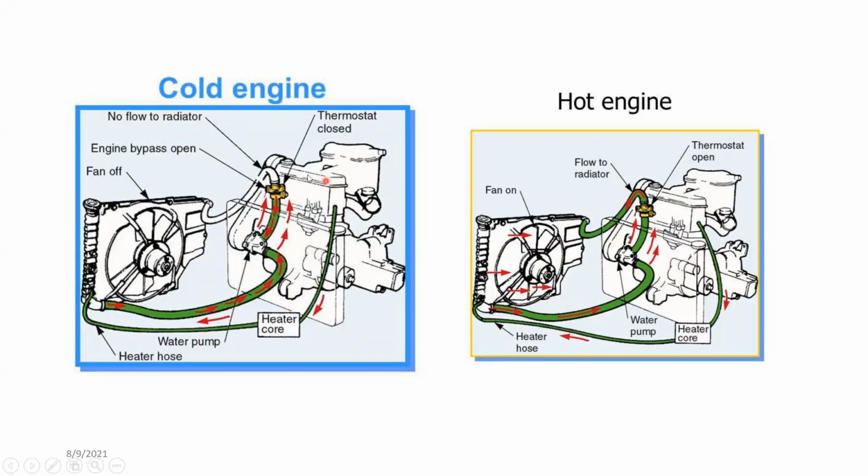Until it comes to the operating temperature, this thermostat valve will not open. Once it gets to the operating temperature, it will open completely and the water will start to flow through. Okay, so this is how the operation is. I'm sure you might have already learned this in your practical or video practical.